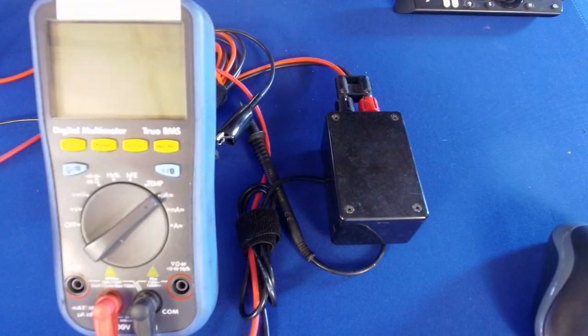One way that you can find it is by using this meter and the cob box, as I indicated in my first episode. So what you can do is disconnect your SLC circuit and go polarity conscious on the positive and the negative. What you're going to read is the current ramping up, and then it's going to slowly drop and stabilize.